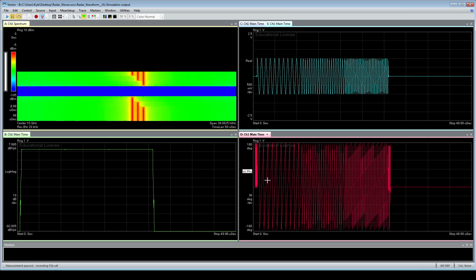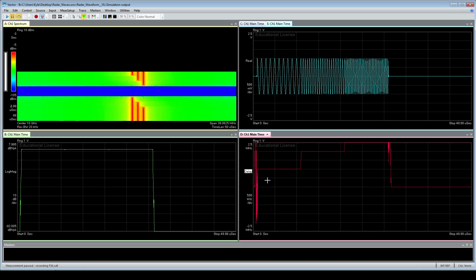We can look at its wrapped phase down here as well. We can look at its unwrapped phase if we wanted to. We look at its I and Q, and there we go. And the delay is, again, a neat way to see this. If we scale it up, the delay plot is really handy for analyzing radar signals, because we can see